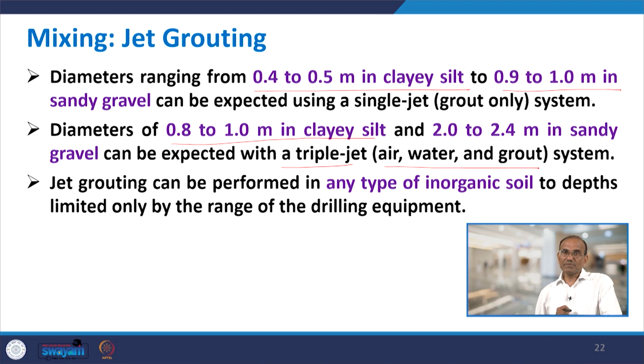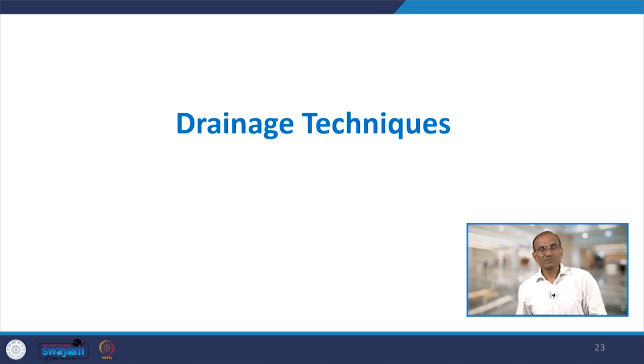So, the jet will consist of air, water and grout system. Jet grouting can be performed in any type of inorganic soil to depths which are limited only by the range of the drilling equipment. So, this was about mixing and grouting techniques.